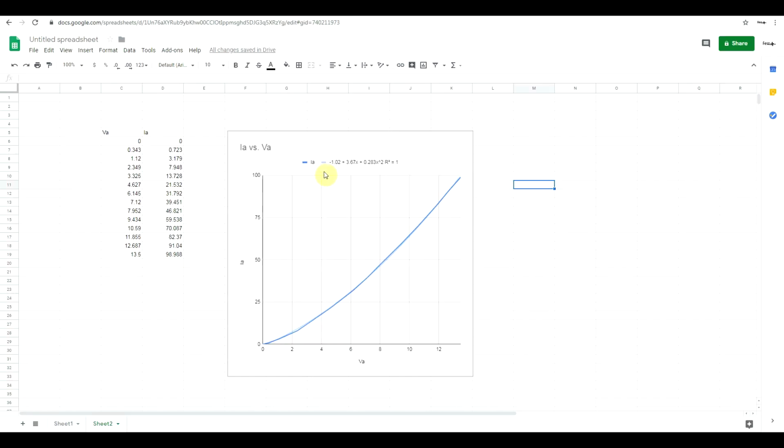Now at this point, there's 2 things we can do. Either we completely neglect this -1 term, and that will give us an error of around 1 milliamp, or we get our diode to start conducting only when this graph hits 0. So basically figure out what are the solutions to this equation, and take the one that is a positive value and get our diode to conduct at that point. Or I can try to take out the points yet again to get a better fit. Let me try that for one moment.